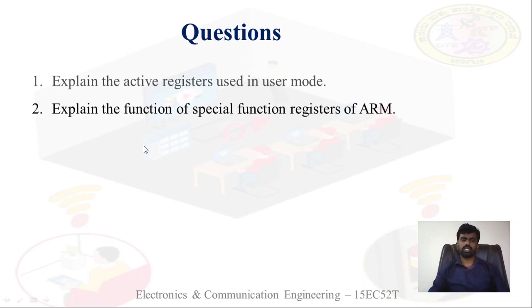Next possible question is, explain the function of special function registers of ARM. What are the special function registers in ARM? There are 3 special function registers: R13, R14 and R15. So stack pointer, link register and program counter. For this question you need to explain those 3 registers.